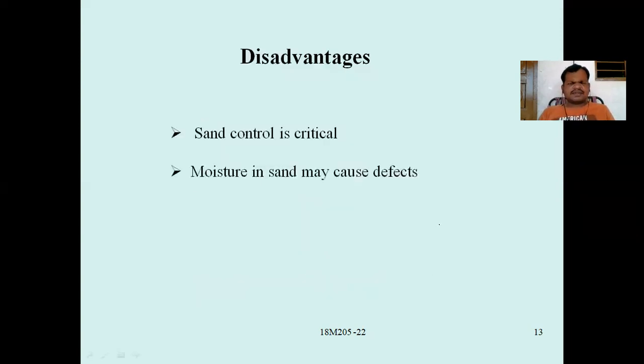Coming to disadvantages, sand control is critical, and moisture in sand may cause defects. Because when we have wet sand, it will disturb the pattern and the prepared mold cavity. When it is dry, it is very strong compared to when we have moisture.